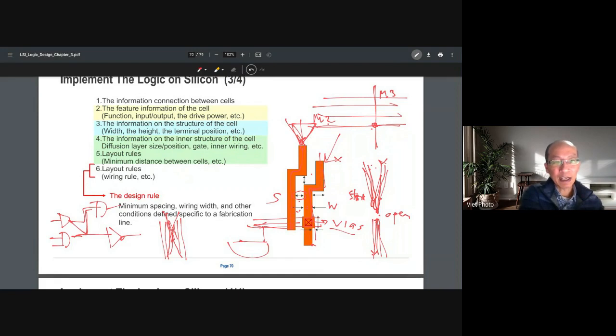You see that? Now you have the contention bus, right? If this one is touched like that, the circuit fails, or this net will have an undeterministic value. Because of it, they need to have a spacing rule, which is you cannot draw two wires next to each other too narrow, too close to each other. It needs to be at a certain minimum distance, and so on. So there will be a rule like that. So that's a design rule.